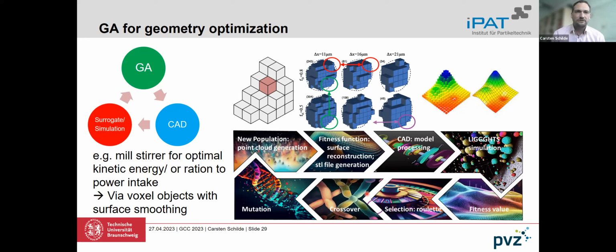So we have our rotor geometry of the stirred media mill, and during simulation, we are trying to evolve this geometry, the disk with the holes, towards one which has the same energy input, or the same power, and the minimum specific energy for our rotor system. How we implement it is given here, the whole principle in these colored bubbles.